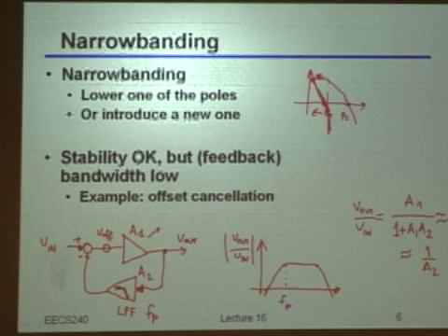And so if you really wanted to cancel, potentially, what you want to do here is actually be really happy about a very low frequency pole, because you don't want to damage your signal, right? You don't want to cancel your signal. You just want to cancel the DC component, your offset. So potentially, how much gain would you allow in the path? Like, okay, you could have here, I don't know, 100. Here you could potentially have, I don't know, 1,000. But okay, so how much, right?